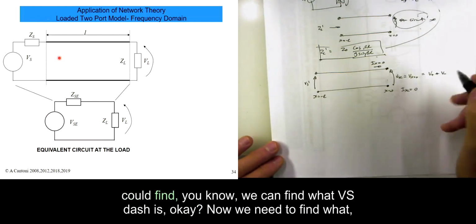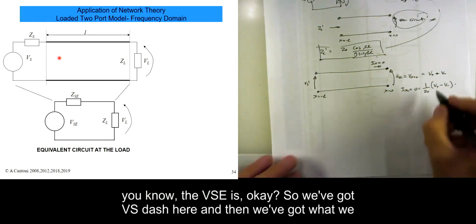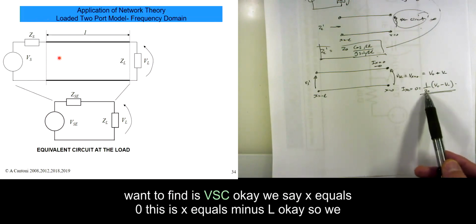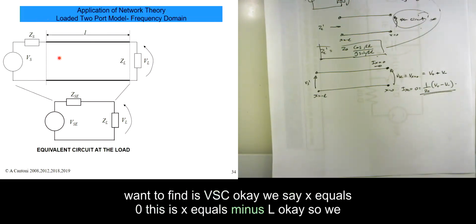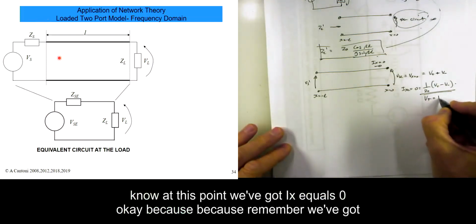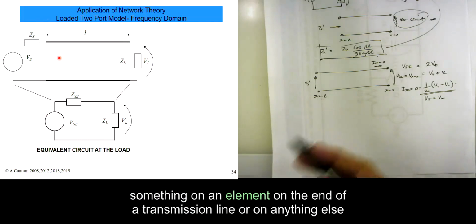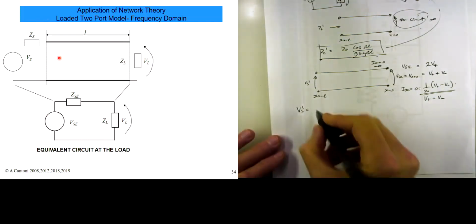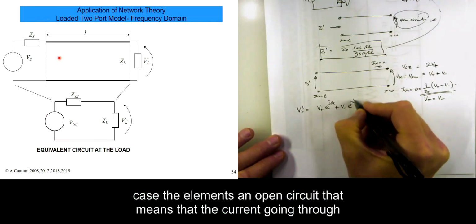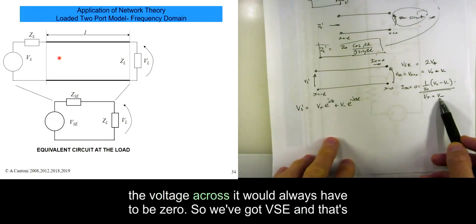And from that we can find what VS dash is. Now we need to find what the VSE is. So we've got VS dash here, and what we want to find is VSE. We say x equals 0, and this is x equals minus L. So we know at this point we've got Ix equals 0, because remember we've got infinite impedance here. Whenever you put an element on the end of a transmission line or on anything else, the VI relationships are forced to obey this particular element. In this case, the element's an open circuit. That means that the current going through that element always has to be equal to 0. If it was a short circuit, the voltage across it would always have to be 0.